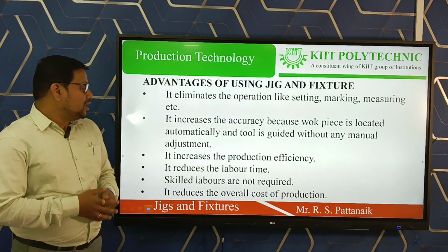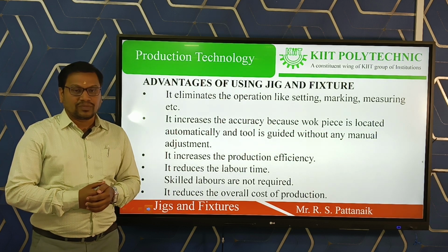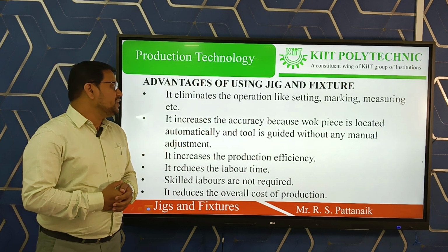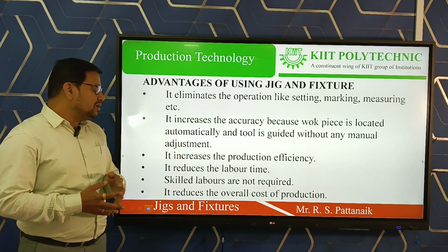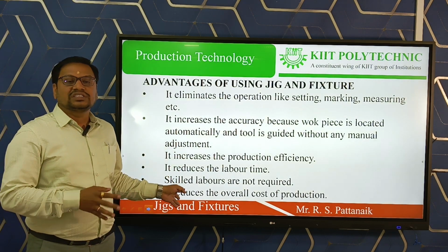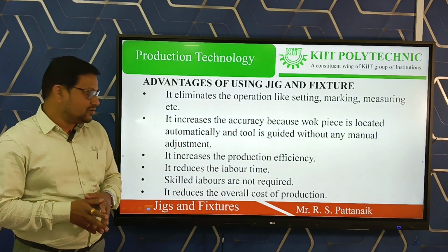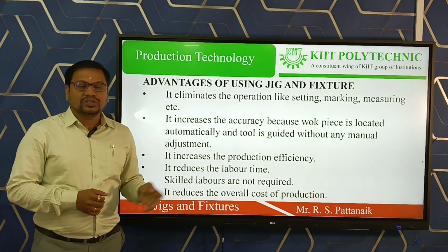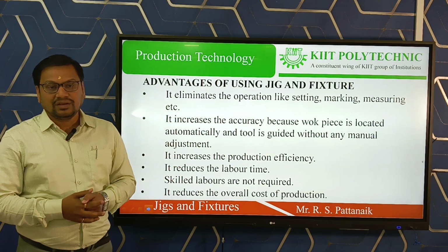It also increases production efficiency. The labor time is reduced, and no skilled labor is required for operating the jig and fixture. So it reduces the overall cost of production. These are the basic advantages of using jigs and fixtures.